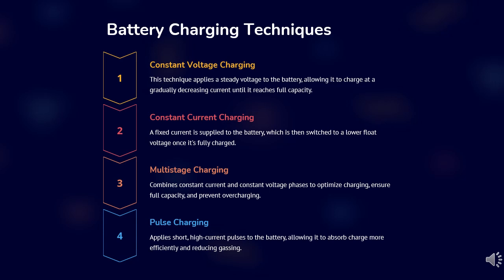Taper current. This is charging from a crude unregulated constant voltage source. It is not a controlled charge as in the V taper above. The current diminishes as the cell voltage back EMF builds up. There is a serious danger of damaging the cells through overcharging. To avoid this, the charging rate and duration should be limited. Suitable for SLA batteries only.